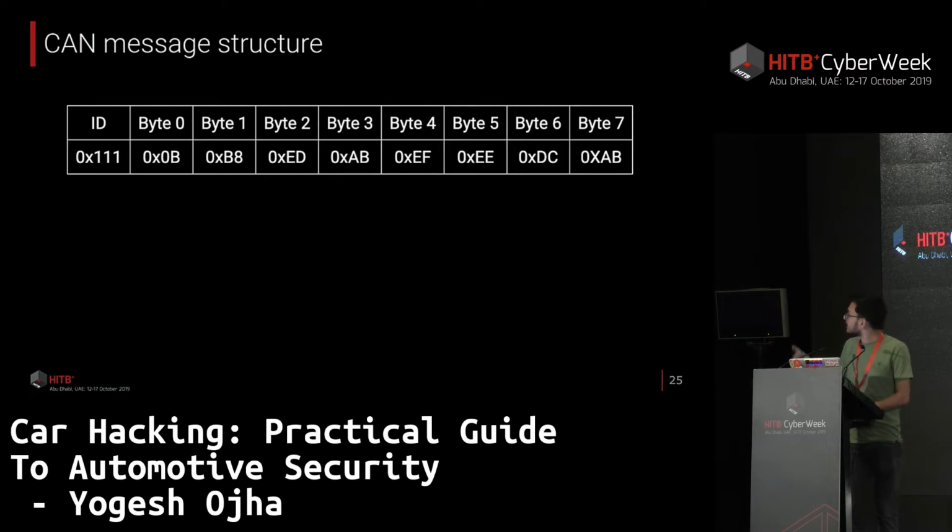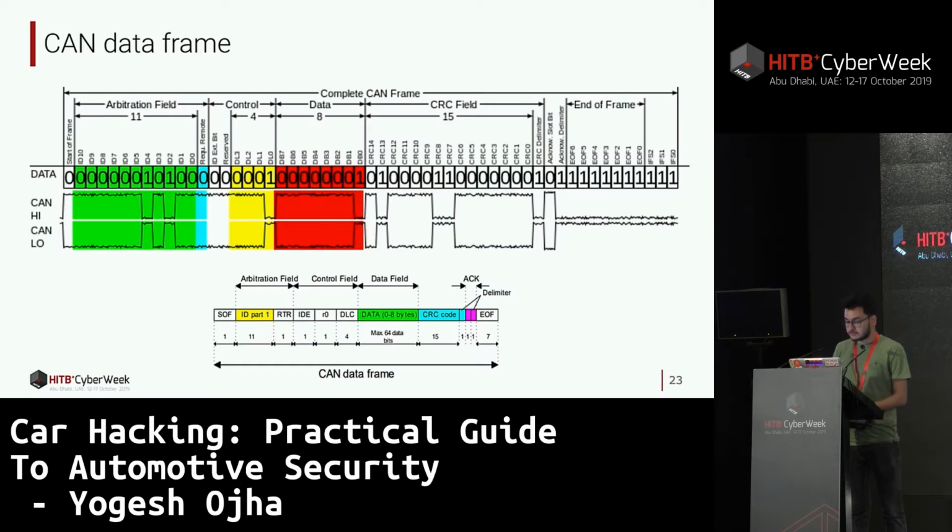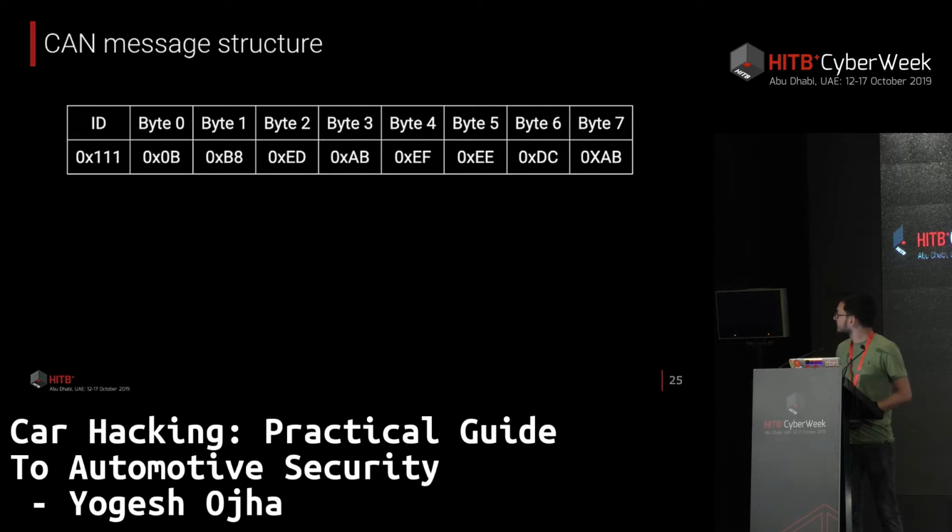So now this is how exactly the actual CAN message packet looks like. In this, you can see that the message is of 8 bytes. The one I told you earlier, the message is always going to be of 8 bytes. If you see here, the message, the one in the red color, is of 8 bytes, right? This is the same zoomed, magnified version of that.